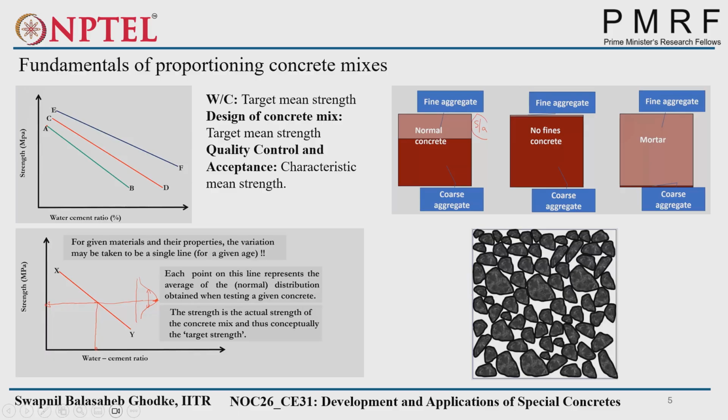Whenever we want to get some workability, these voids should be filled with the paste or the mortar, and there should be some amount of excess paste or mortar, which can create some thickness surrounding each aggregate. This decreases the direct contact between the aggregates. Why? Because of the thickness of the mortar or paste film, it creates lubrication. Because of the enhanced lubrication, the workability will be high.